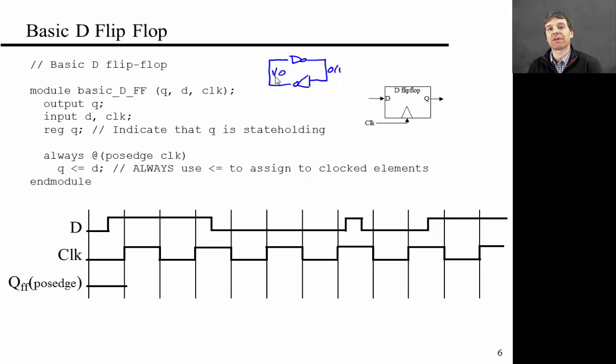Of course, it's not really interesting because you can't really talk to it. But you could imagine doing something slightly more sophisticated where you have two NAND gates that take external inputs and you connect them, something like this. Now you can actually change the values held in these internal wires by changing the values on the inputs. This is not, I should say, a flip-flop, but it's the basic idea behind a flip-flop. You're creating little feedback loops between inverters, and that serves as a state holding element.